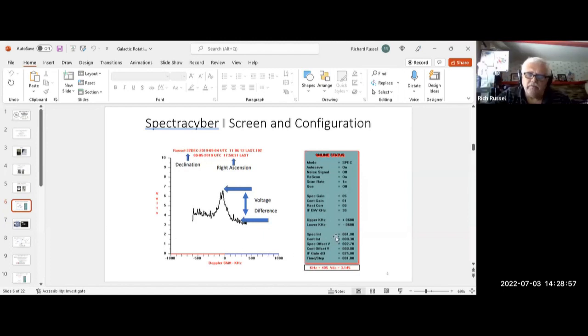With the offset numbers, before it goes to the screen or the data, I can subtract a certain amount of voltage across the entire data. The other interesting thing is that if I do that, I have to restart the scans. I can't do that while I'm running scans. I have to reset, and it's not a problem, but if I want to play back, then it is a problem. Let's see, IF gain.